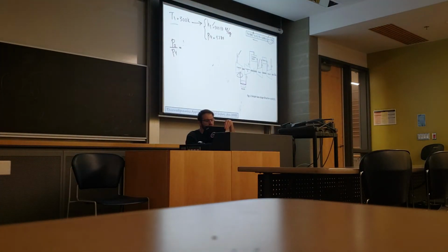We have this pressure ratio definition: P2 over P1 equals PR2 over PR1. We have this as 3, right? So we can say that PR2 equals 3 times PR1, which is 4.158.